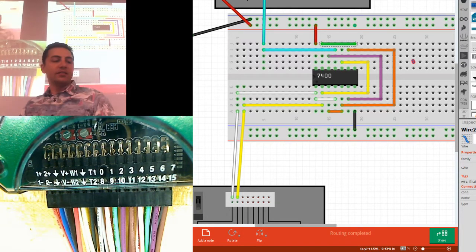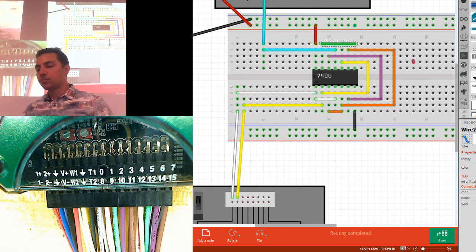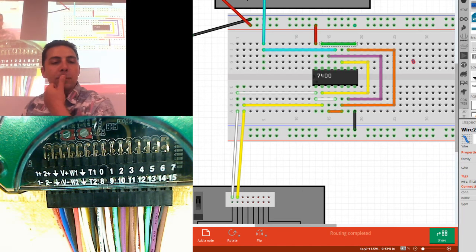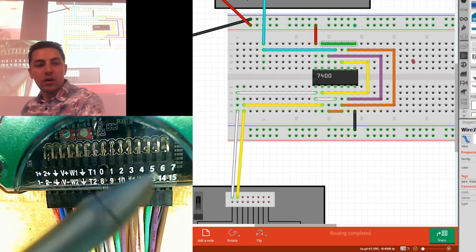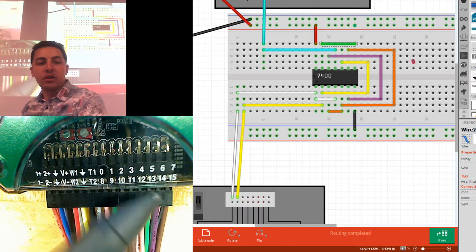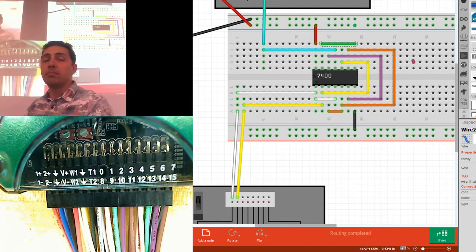All right. This, everybody look in front of you. There should be a rainbow cable with a little squid on the end of it. Okay. It's the same squid, same markings, just an extension cable. It's split up into two halves. On the right half, you have these numbers 0 through 15. Those are your digital I/O pins. Digital I/O means they can read or write digital signals. They're I/O, they're input or output. So you can use them to read in digital values or to send out digital values.